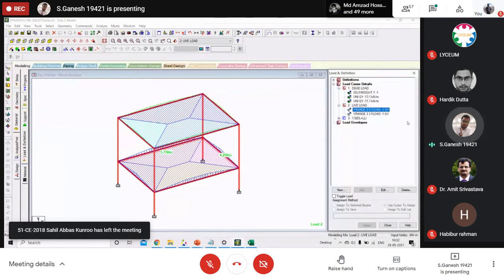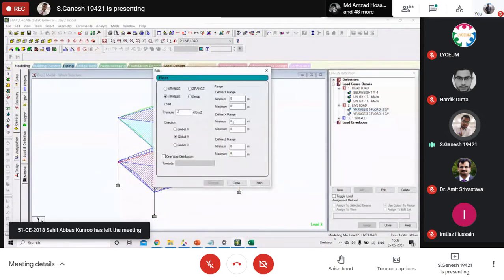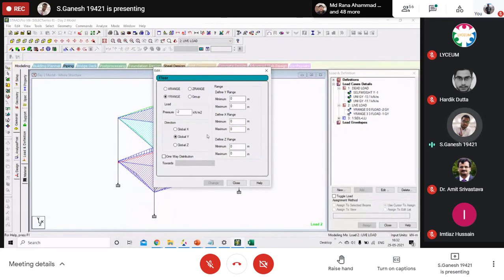Now when you see the ground floor, this axis is the most important part. A number of students make mistakes here. Since the model is a very simple model, a one room set, you're not using any range over here. So you're using X as 0, Y as 0, Z as 0. So no changes in this part. But make sure when you have different sizes and thicknesses of building slabs, I request you to understand this X range and Z range.